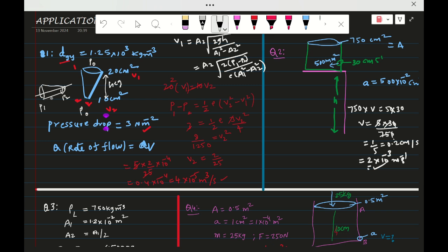The difference in the pressure energy means the work done, P1 A1 delta X1 minus P2 A2 delta X2, which equals PdV. That will be the answer here, P1 minus P2. If it is taken like this, H rho g will be in the place of P1 minus P2. That's why I have given these two equations, right? So substituting, you will get the answer.